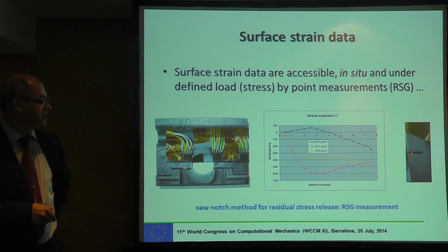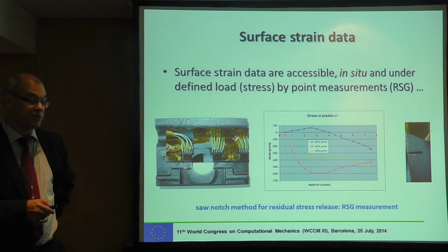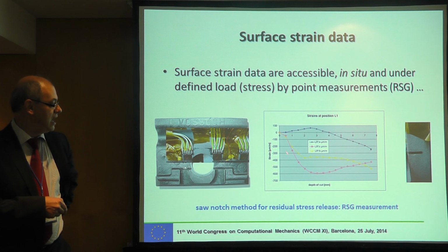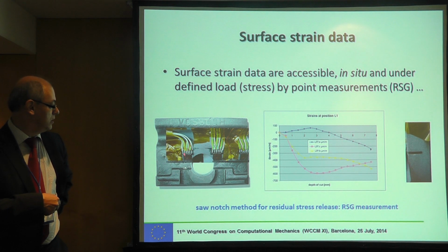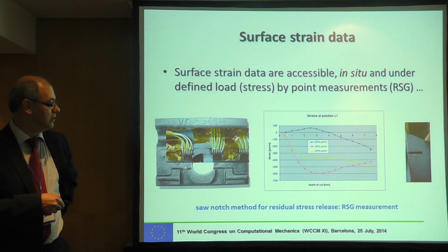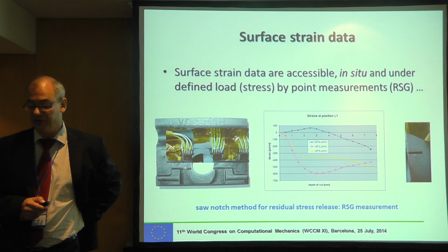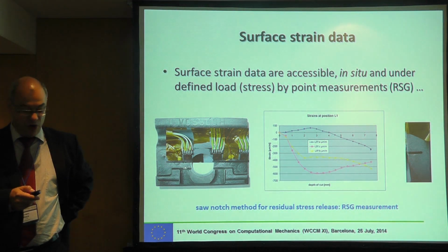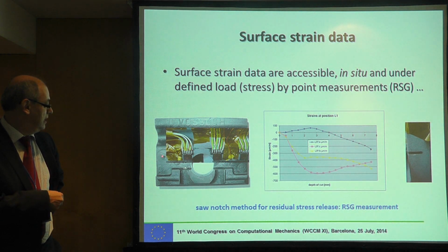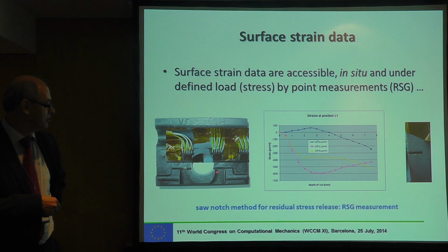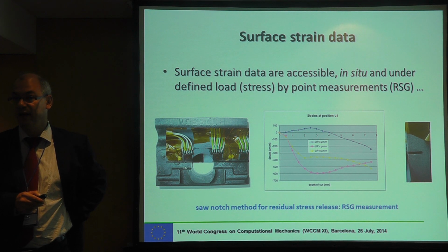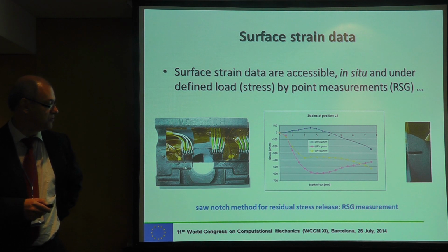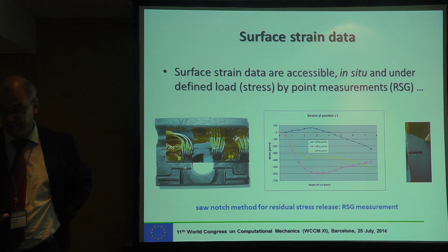The experiment we have is a saw notch residual stress release experiment. So we gradually increase the notch here and observe. This is just one of the rosettes. You observe the evolution of the strain in 3 different directions. Well, this can give you some hints. However, you don't know exactly, because residual stress, this is an injection molded component, is not quite clear where they should appear and to what size. So you see, we go something like to 600 microstrains here in compressive.